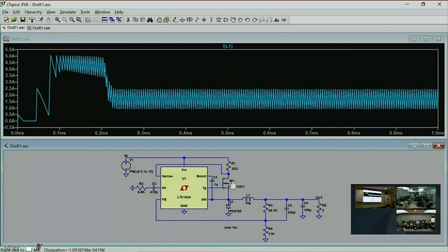Here's the in, there's the inductor, here's the output. Okay, so in a buck controller, you have an inductor connected to the output. The other side of the inductor is alternatively connected to the input or to the ground. One of these two switches conducts, and the ratio of time the inductor spends connected to one rail or the other determines the voltage bucking ratio.